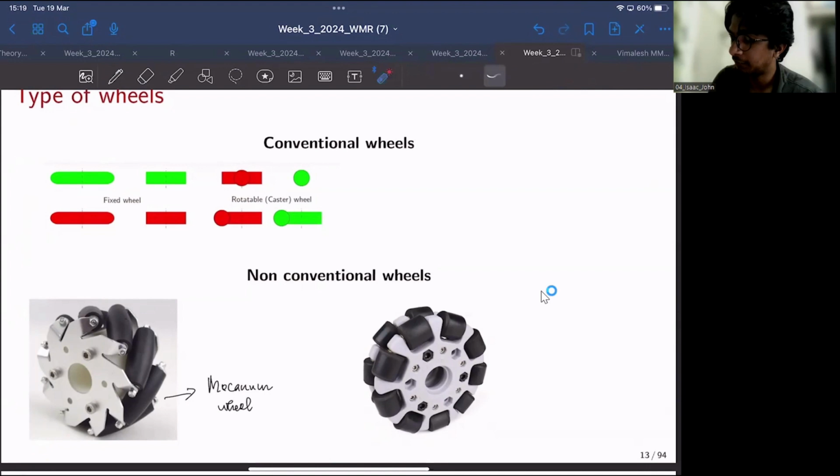See, if you consider this to be the primary axle of the wheel, where the wheels will be powered. On the periphery of these wheels, you will see these passive rollers, these barrel-shaped black-colored rollers. These are not driven; they are actually passive. So that basically enables this wheel to slide along this lateral direction. Apart from the rolling motion, these rollers will also permit the wheel to slide along this lateral direction.